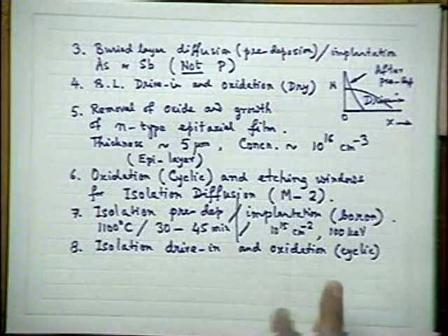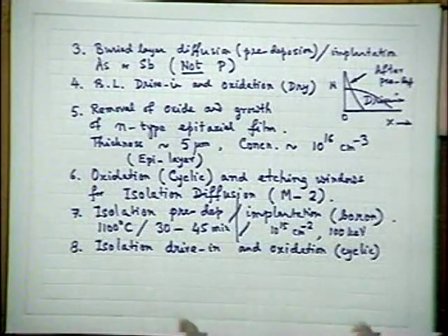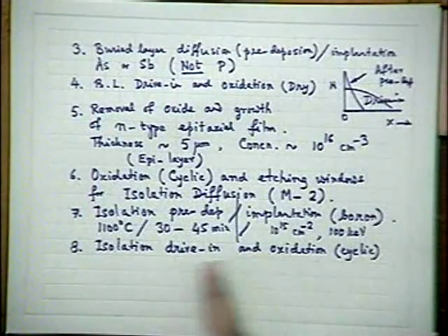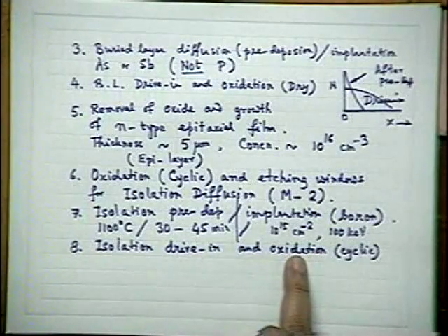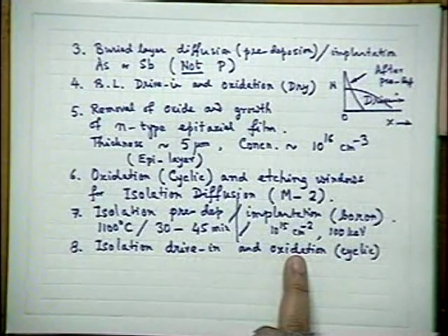And secondly, in the next step, we need an oxide film again for masking purpose. So every time between two processes, I need a thick oxide around 3000 to 5000 angstrom. Therefore, we combine mostly the drive-in diffusions with oxidation. Please remember this. That is why I write separately, but please remember it is the same process. Same process which drives in as well as oxidizes the silicon surface.